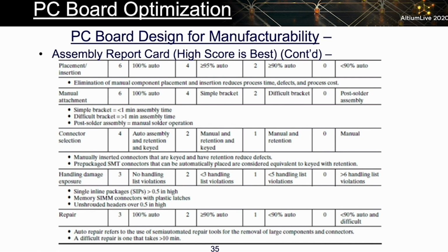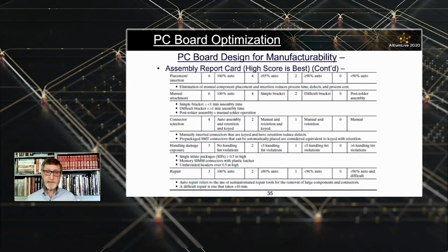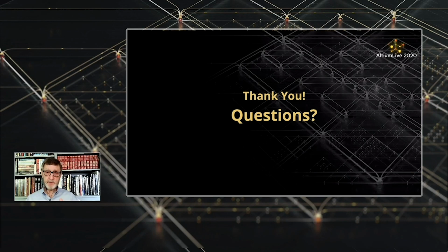Get to know all of this stuff and get to know it well, and get to know the impact you have on fab and on assembly, and know the breakdown that you will create at the fab and assembly house and the cost impact that you have. You need to know those processes inside out. If you don't, you're compromising the overall quality of your circuit boards. Know them, respect them, know what to do to minimize thermal stresses at the assembler, stresses on components, fab processes, all of these things. Know how to design to minimize those effects. Thank you so much for your time.